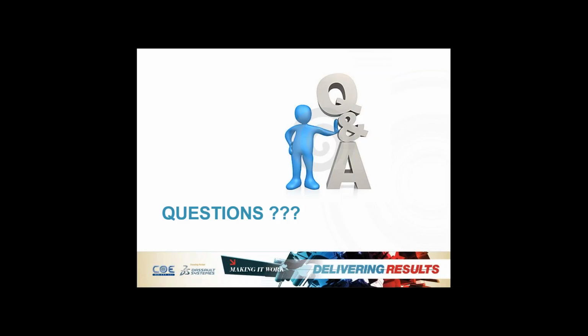So like I said very quickly, there's a tool in CATIA called the deviation analyzer, if I'm not mistaken, between the French and English version. That tool allows you to actually compare your CAD to the scan. So you'll know if there is any deviation, and of course it might have some, but whether those deviations are outside your tolerance. So you can then go back to your design and modify it.